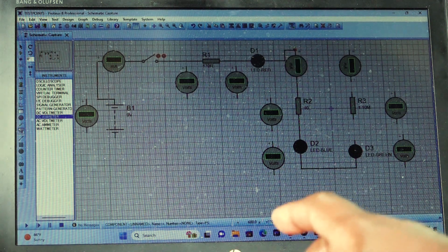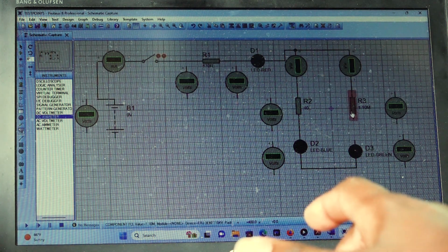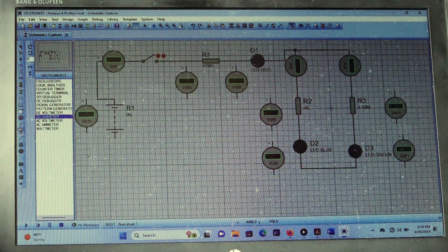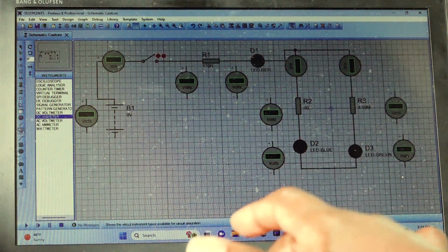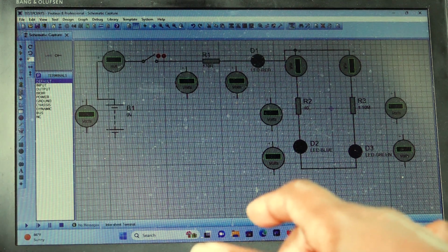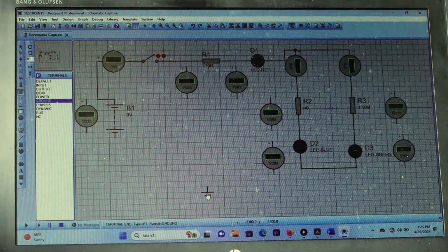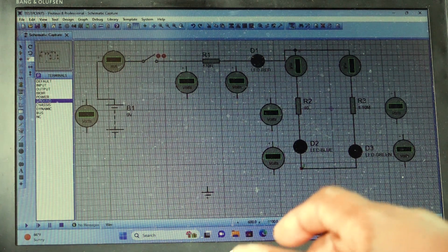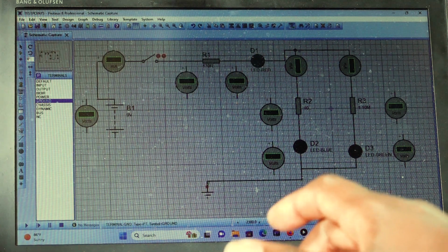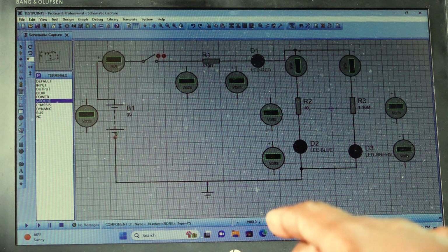Then here it is. This is our junction. Join this terminal with this one terminal for the DC milliammeter. Then join this terminal with this terminal. We forgot one of the important parts, which is ground, right? So where do we get it? In icon number 8. In icon number 8, which is written as what? Its name is terminal mode. So we choose ground and place it there. So now we have our network here. Then we are going to connect with our ground. Then connect the ground with what? With the negative terminal of the battery.